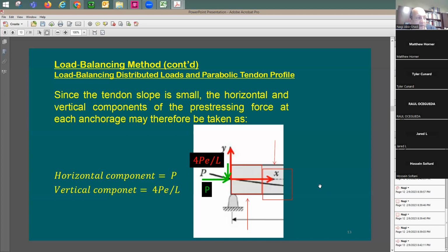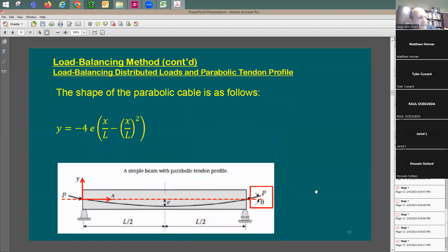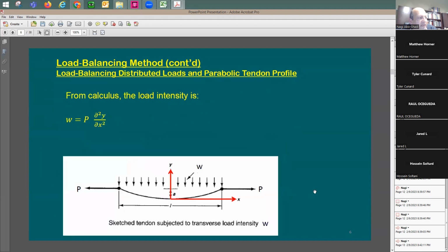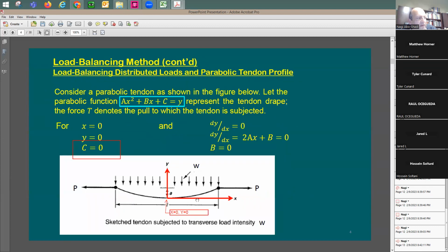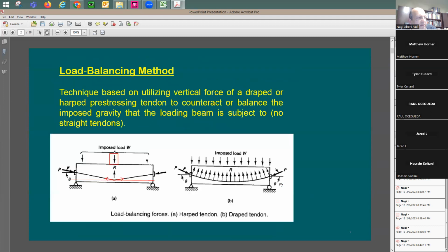Yeah, absolutely makes sense. Look at this beam here, from the load balancing thing. This gave me the applied force, right? Let me go back here. Here's the applied force. What does it do? It creates shear to bring this piece up and this piece down. So here's the beam. One piece is going to be here, here's the other section of it, right? Let's say, and what this loading is doing is trying to push this down like this, correct? What is this trying to do? This loading, it's against that. So actually it's doing this to the beam.